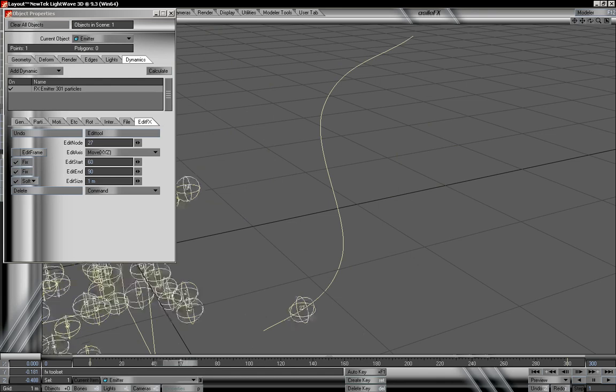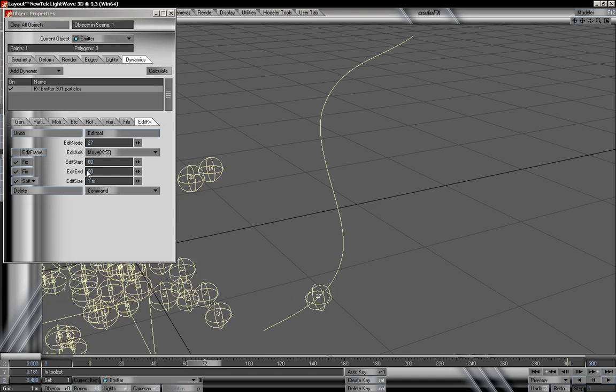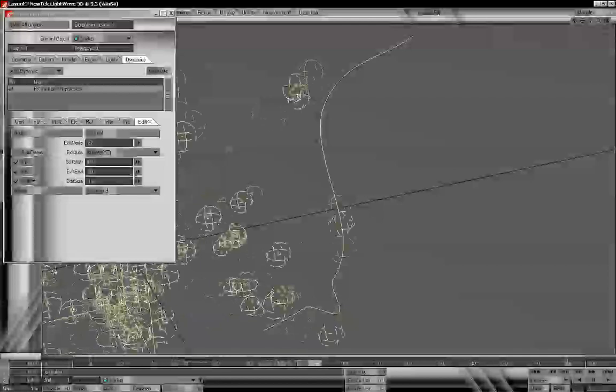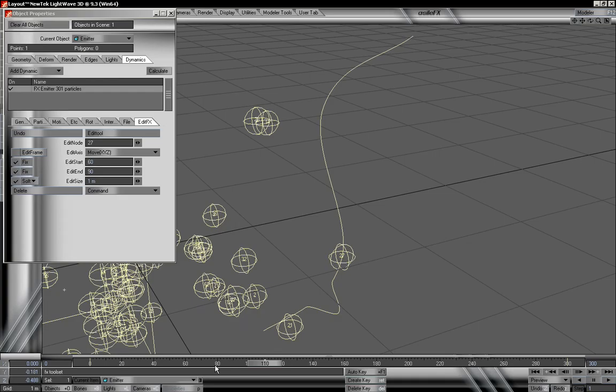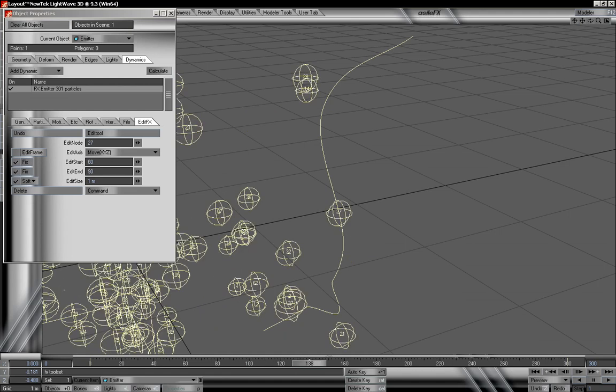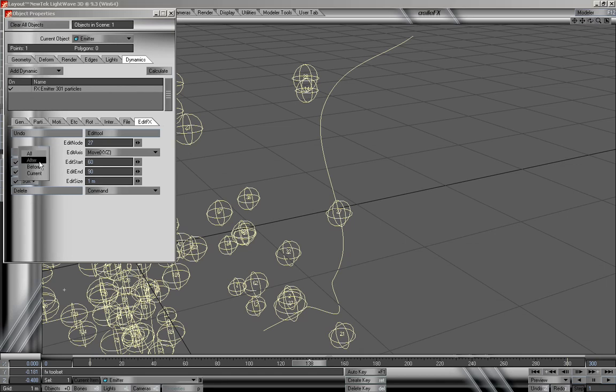Once we move into frame 60, between 60 and 90, and now I can click, and now I have the ability to move and create our new keyframes and our additional motion for our particle. And once we move past frame 90 now, if I try to move this, we can see that I can't. So those fix options are really helpful. We can edit frames, we can do after.